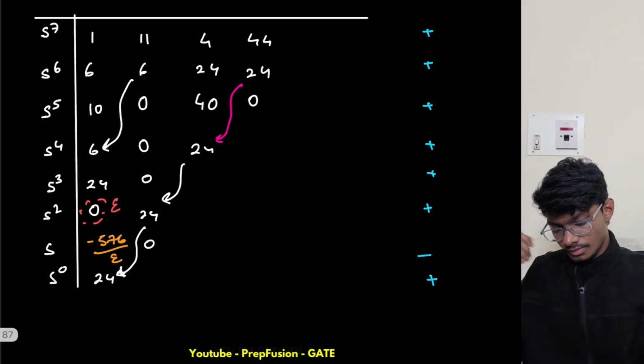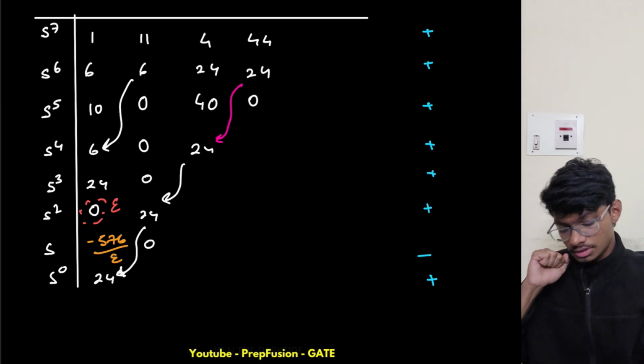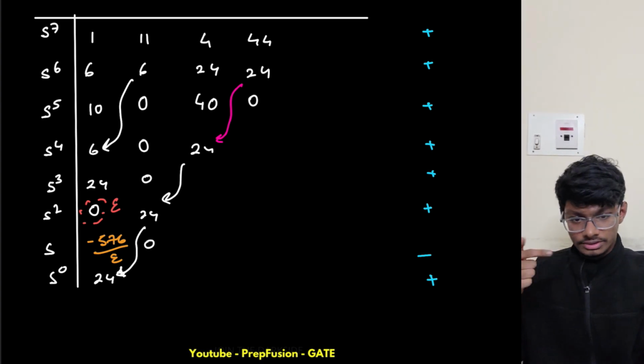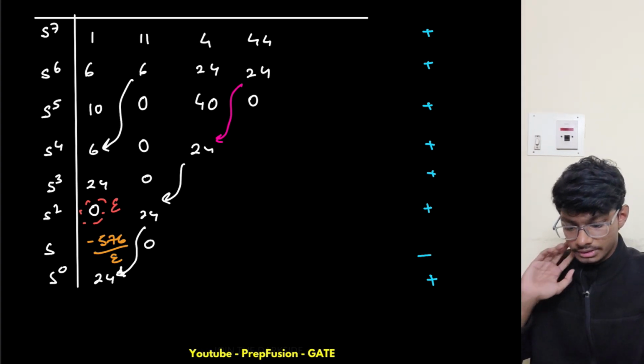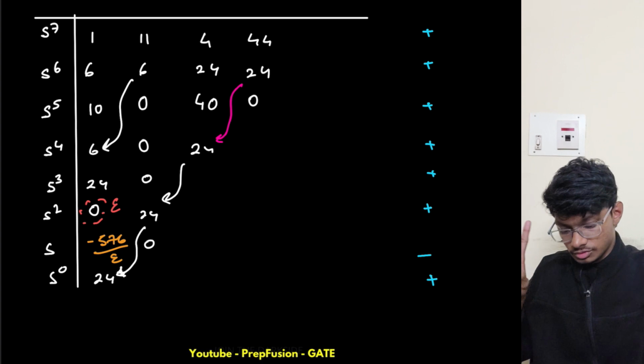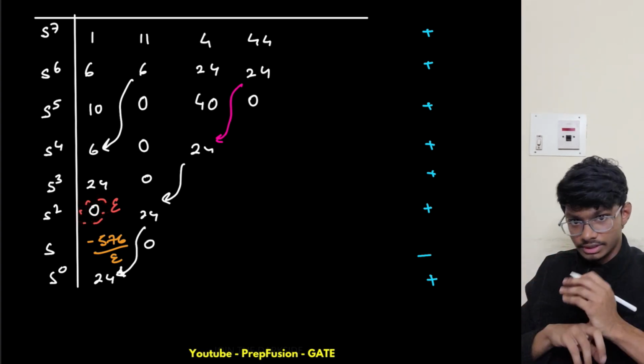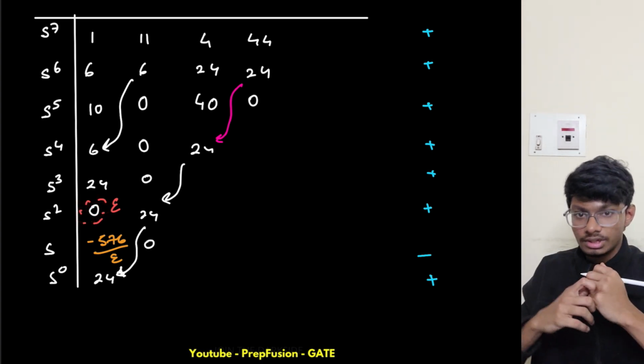So right now, what's next? The next thing is we got this, basically our system is not stable, that we know. Now let's come back to the roots. Let's prove that I have two poles in the right half plane. So you assume this as positive and then you follow along, right? That is the main procedure, a small positive number, that you follow along.